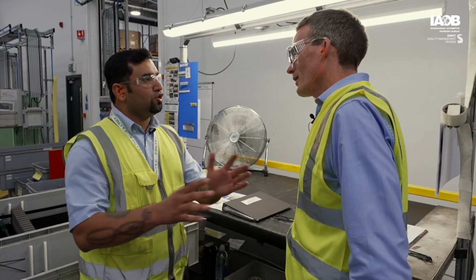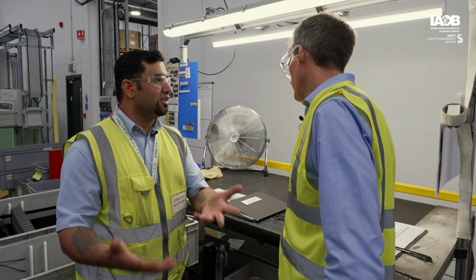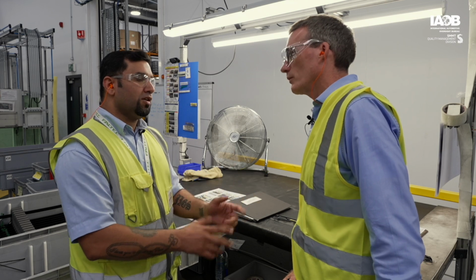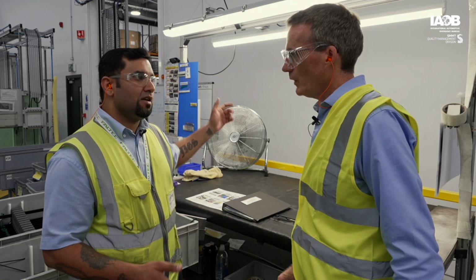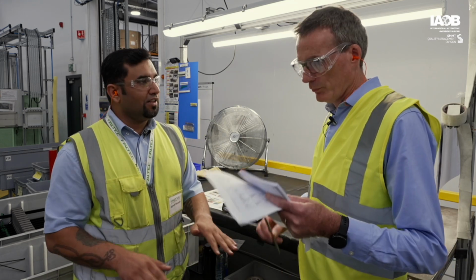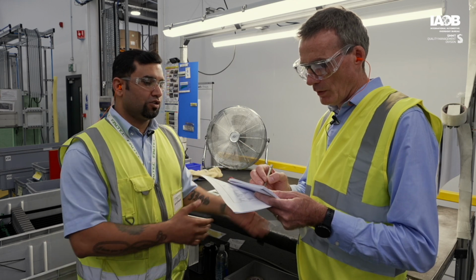was there any issue with the lines? Was there an issue with the glue? Was the glue in expiry or not? So we check that everything was all right. Then we hold the stock we've got and do a thorough inspection again, making sure everything's all right. We do our tensile test, making sure the force is right. If everything's all right, then we release back to the stores. And that will be our initial escalation point.